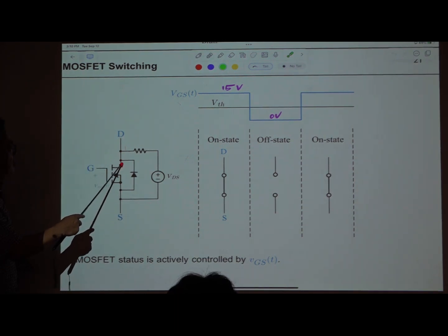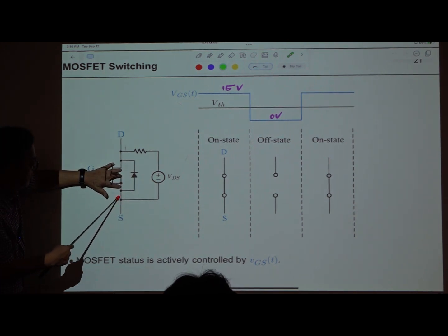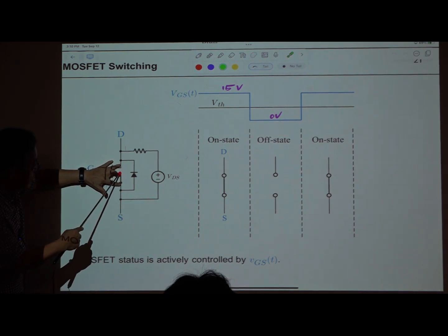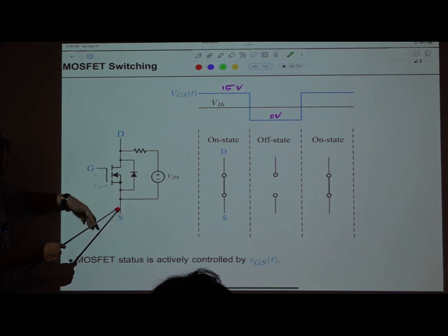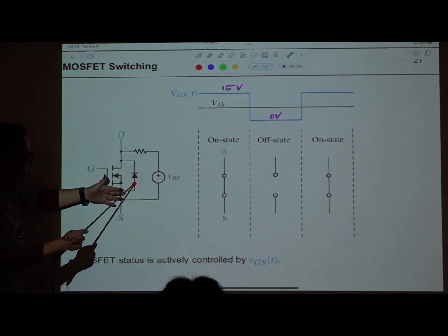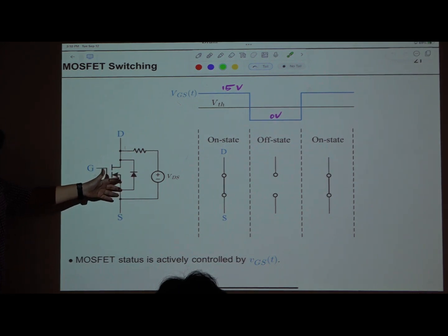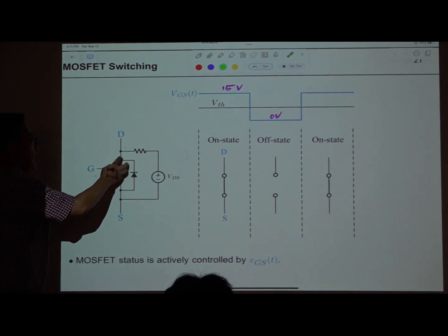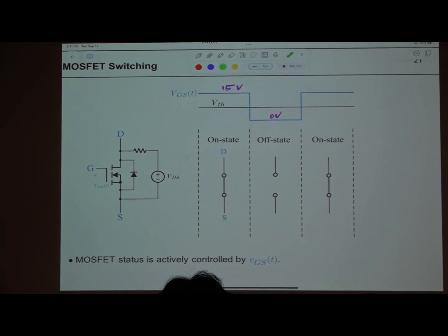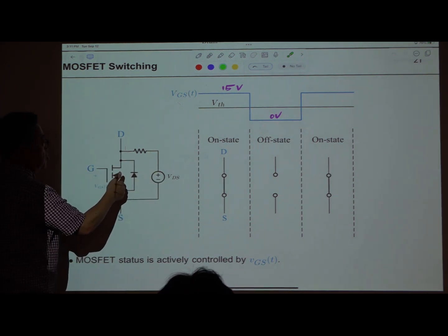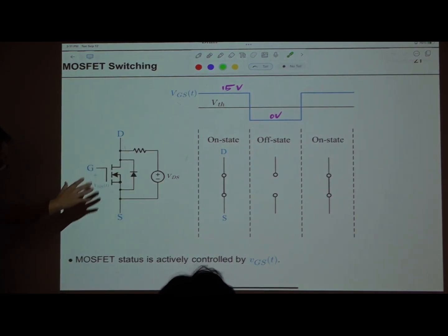Okay. So there is a fixed resistance RDS on, and the current starts to flow in this direction. When the voltage drop across the channel resistance exceeds 0.7, then the diode will be turned on. Then the extra, larger current will flow through this diode because this voltage is fixed. So initially the current goes through the channel and turns on the diode, and later on a large current will go through like this. That is the story. I don't know if that is correct in theory, but that is my assumption. So anyway, partially the current flows through the channel, and the main current will flow through this body diode. All right.